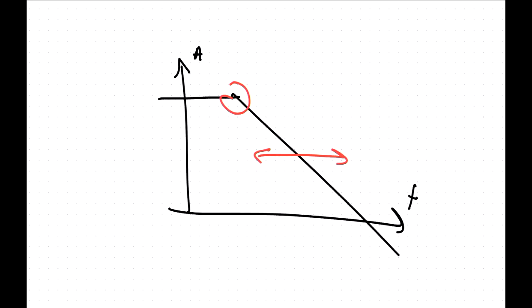You probably want a DC gain of about 1,000, I'd say, so 60 dB, before you can really say, oh yeah, this is a decent op amp. 120 dB is better, but 40 dB is not very good for an op amp. So you might want to put in some more gain stages, even for that.